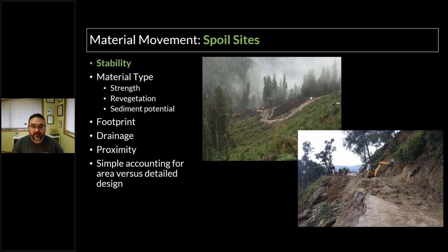That's a very, very large spoil site, and there's a windrow of riprap. I don't know if you can see it at the toe of one of those big slopes. So understanding when you're going to hit certain materials and staging that spoil site so you can put that spoil in the right place. And on the opposite side of that, maybe you want to save your organics or the grubbing from the ground surface to cap that pile for revegetation or reclamation.